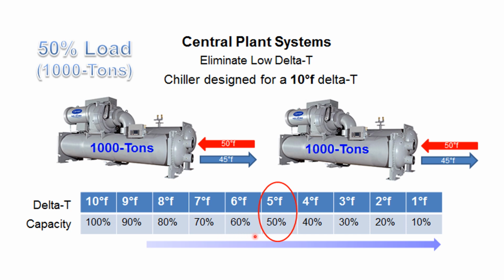Today, if the chiller is also integrated with VFD, at part load conditions like 50% and so on, chiller efficiency goes down. So integrating VFD and these things further improves the specific energy consumption at 100, 90, 70% of its load conditions. But 50%, 40% is not really an advisable condition, which means at part load, my chiller is going to consume more energy.